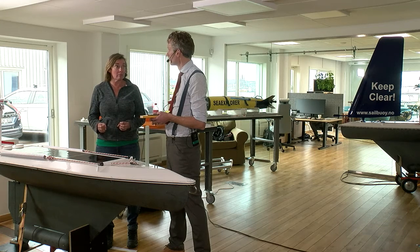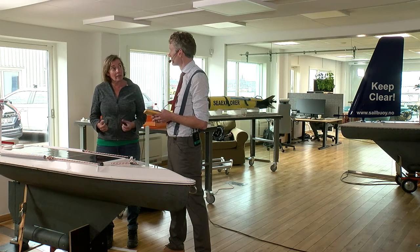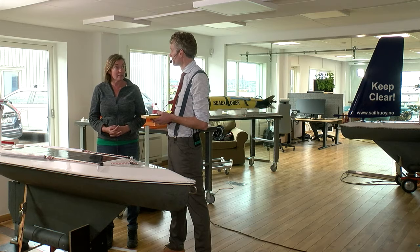Ran is an 8-meter long robot that has a capacity to go out on missions up to 36 hours, which converts to 300 kilometers roughly. And because she is large, she has capacity to have big sensors on her. And I think maybe that is the most important difference between the smaller robots. So Ran can have quite sophisticated acoustic sensors, and she has a CTD that is of the same scientific quality as the stuff that you carry on board research vessels.